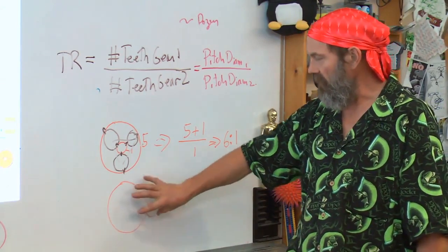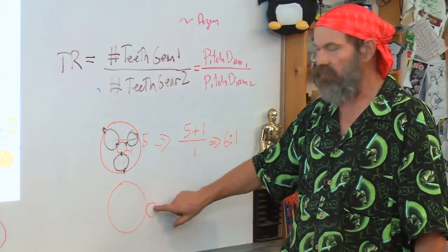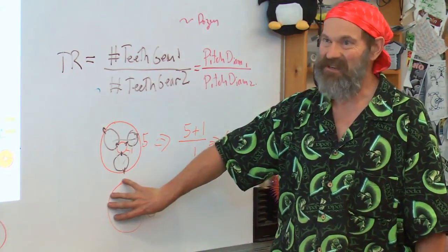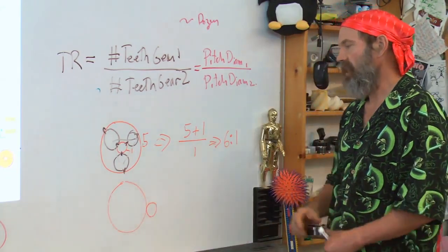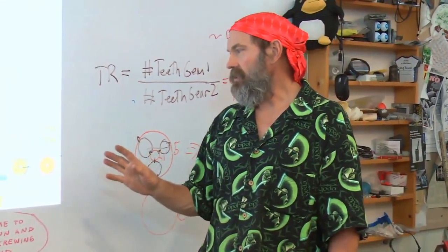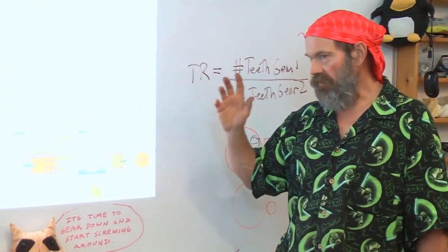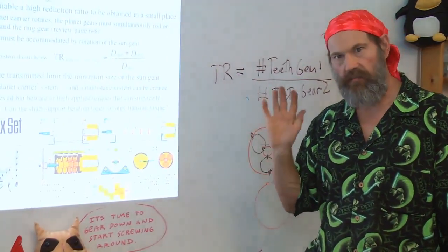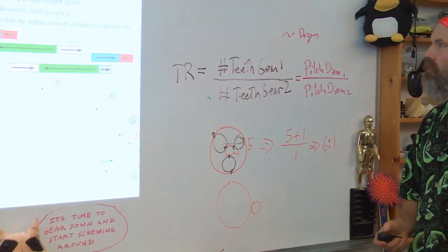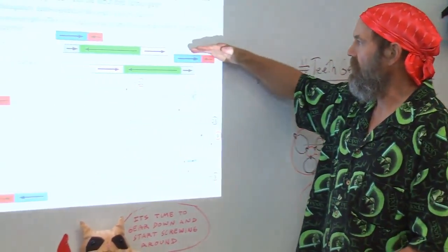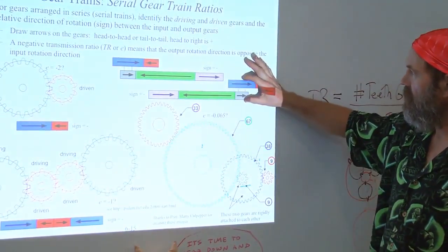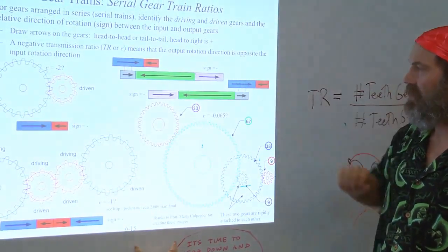And by the way, when you have a big gear being driven by a small gear, the small gear is called the pinion, and the large gear is called the, surprise, gear. Sometimes on really big gears they're called the bull gear. With a planet system, though, you have the additional advantage that it's really easy to get multiple stages. You see, earlier, you have to start stacking things up in series this way, and you start getting some fairly strange radial shaft loads.